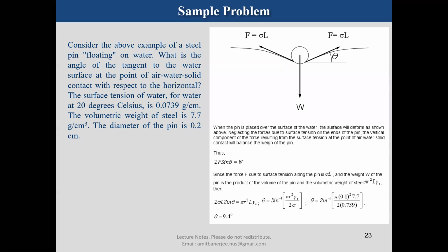Here, the vertical component of the force resulting from the surface tension at the point of the water-air-solid contact will balance the weight of the pin. So basically 2F sin theta will be the same as the weight. Now F, which is the force due to the surface tension along the pin, will be basically the surface tension times the length L.